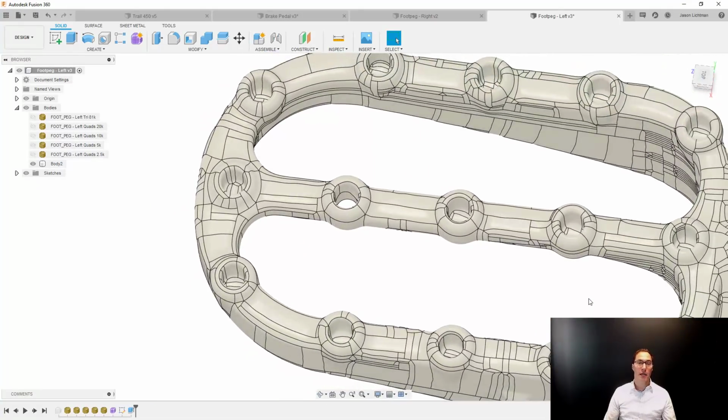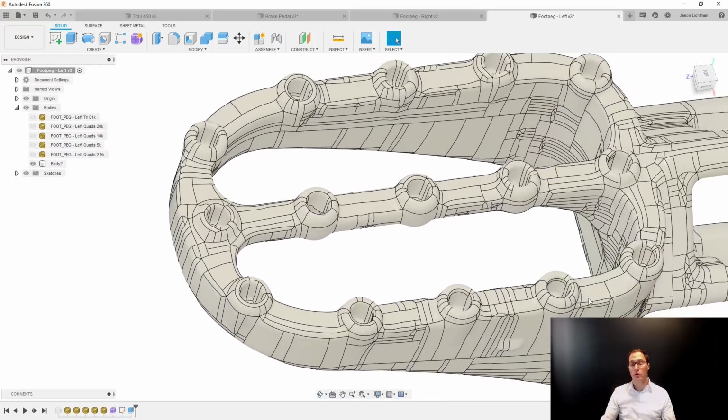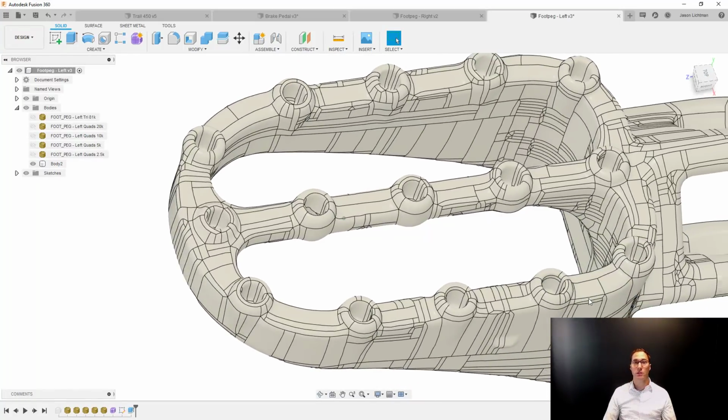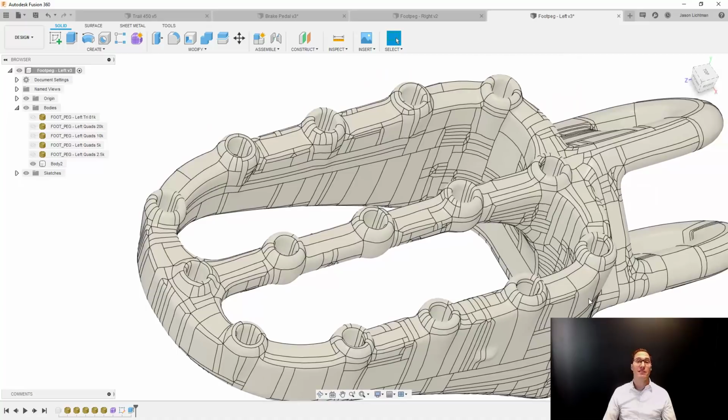So just keep in mind that this is a great workflow for you to use. Again, that's going to be quad mesh to T-spline to B-rep. This works even better for more organic shapes, especially if you want to make some changes to that organic shape. You could do that in the T-splines environment and you'll still get a B-rep. We have two methods left and about 10 minutes, so this will be interesting. But we have two more methods left, so let's show them.